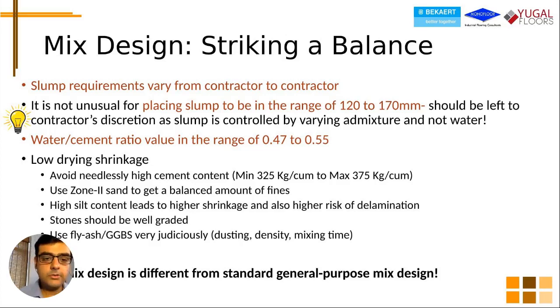Secondly, the water cement ratio should be in the range of 0.47 to 0.55. This is what the guidelines tell us. This is what I agree with as a flooring contractor. I'm very happy to see this point in the guideline, because concrete does need water. In the next slide, I'll talk about evaporation. We need water to prevent plastic shrinkage. We need water for the hardener to bond properly. And a lot of people panic when I ask for a 0.5 water cement ratio.